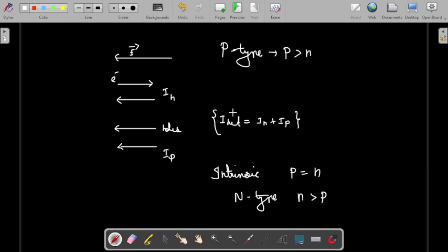We also note that at very high temperature, even the extrinsic semiconductor acts as an intrinsic, because the band-to-band transition, or the electron-hole pair generation, overcomes the impurity ionization. Therefore the doping will be useless, and all the electronic devices will fail. Nothing will work at very high temperature. Even at a very high temperature, the extrinsic semiconductor will behave as an intrinsic semiconductor.